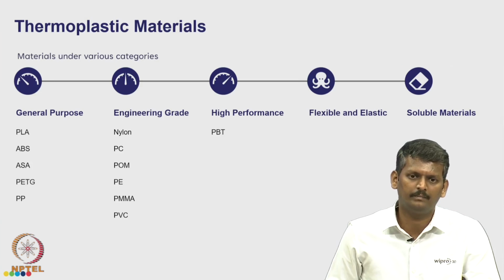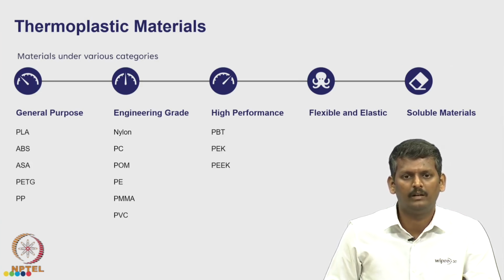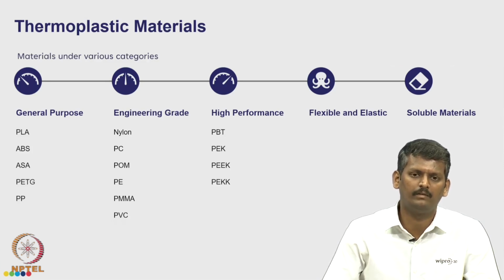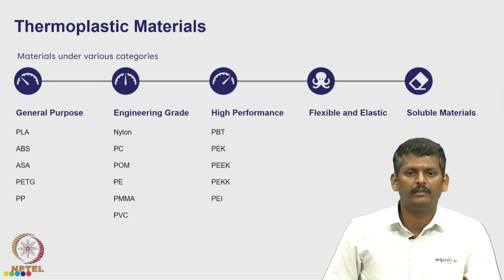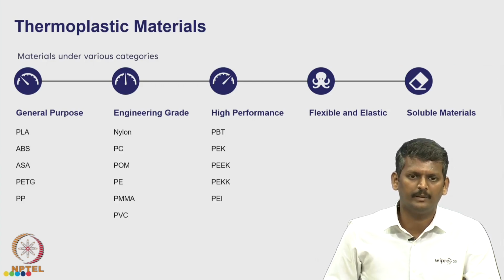polybutylene terephthalate. Then we have PEK, that is polyether ketone, and we have polyether ether ketone and polyether ketone ketone. These PEEK materials are very common in medical applications because they provide very high strength, and it's actually a biocompatible material and used for implant kind of applications also. And we have polyetherimide, PEI, in the high performance category.